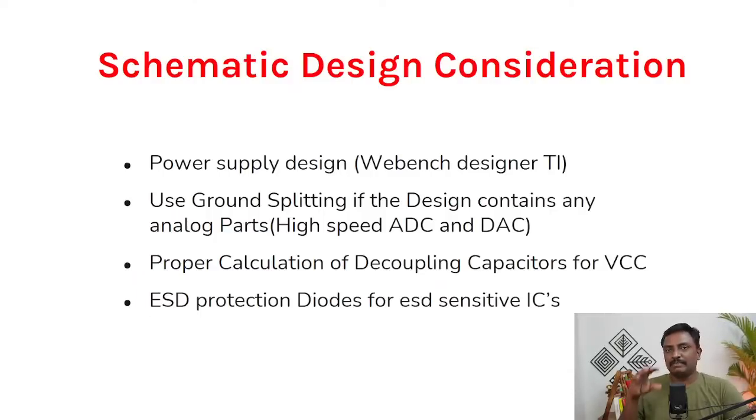So coming to the schematic design considerations, like the power supply design, the first thing is you have to take care of the power supply design. You can use the Texas Instruments WEBENCH Designer, and you have to take care of the ground splitting whenever you have analog grounds and digital grounds. Whenever you have high-speed ADCs and DACs, you have to do the ground splitting, and proper calculation of the decoupling capacitor. Every VCC should have a decoupling capacitor attached to the pin, so that you avoid noise.